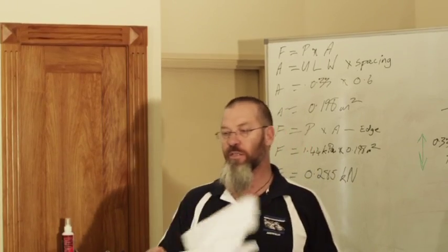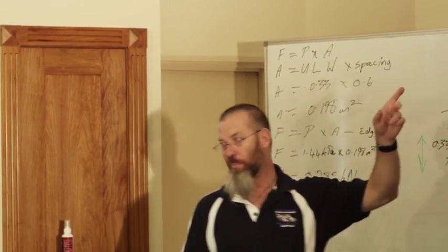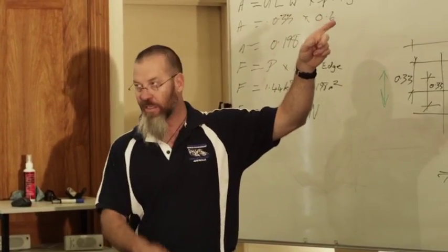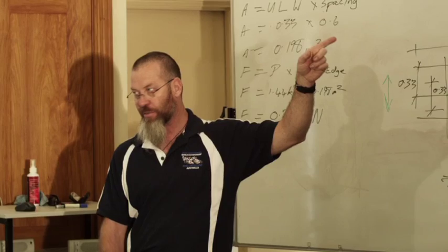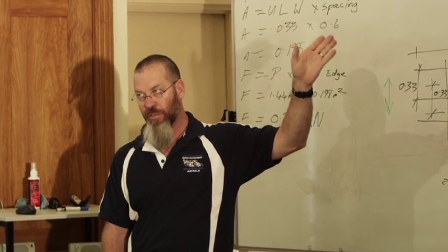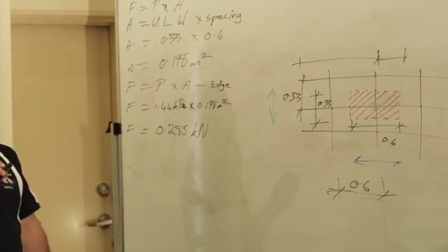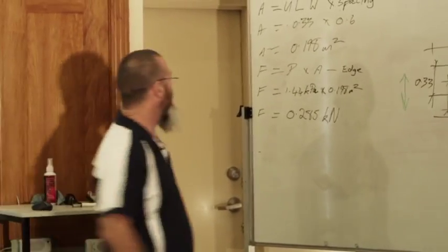So what that means is that when you went back to that information we wrote down before, our spacing's still the same. Our rafters or trusses were at 600 centres, but because it was a metal roof, our batten spacings now will be at 900. So this won't work. All right?